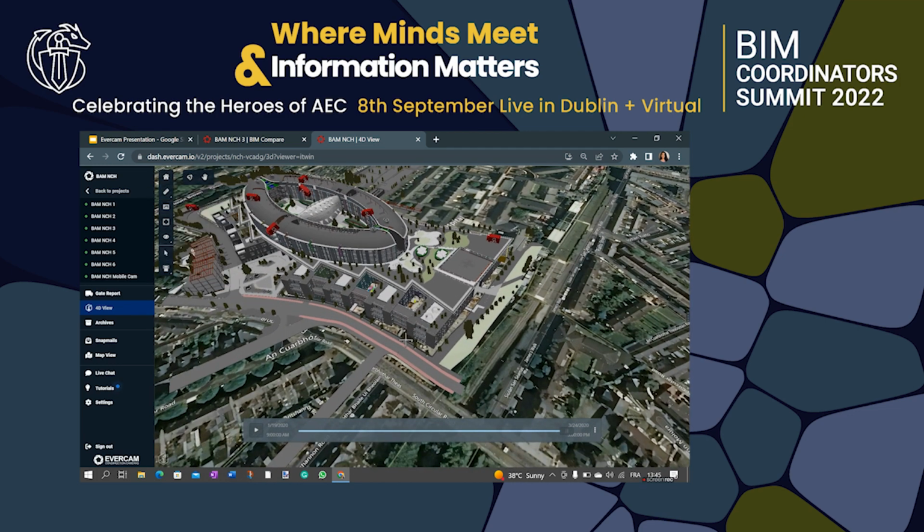If I want to measure distances, I click on the first point and then on the second point, and I have my distance. I can measure inside and outside of the BIM model. So here I measure this distance on the BIM model, but I can as well measure the distance between, for example, my project and the neighborhood. So I can measure anything inside and outside my BIM model. And I'm able as well to measure areas. So I can choose, for example, random points here. My area is highlighted and I will have it here.